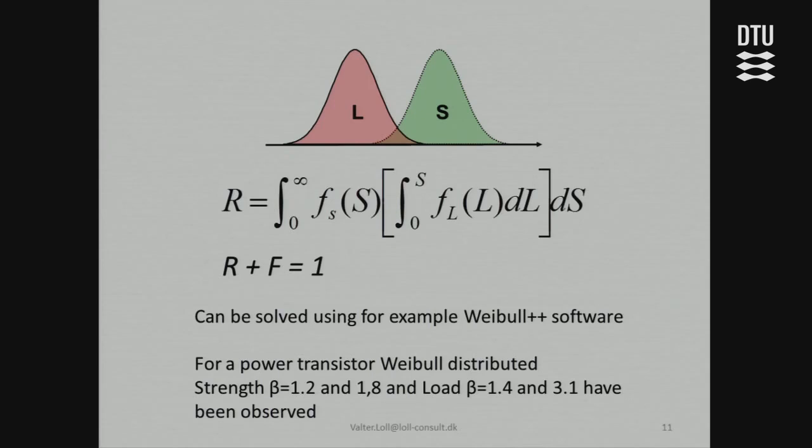I did this simulation for plastic parts using the load strength for different safety factors, 1, 2, and 10, and here 1.2. And I could calculate the percentage of failure for different orientations of the flow in the plastic molding. So I could give design guidelines for how much design margin was needed.